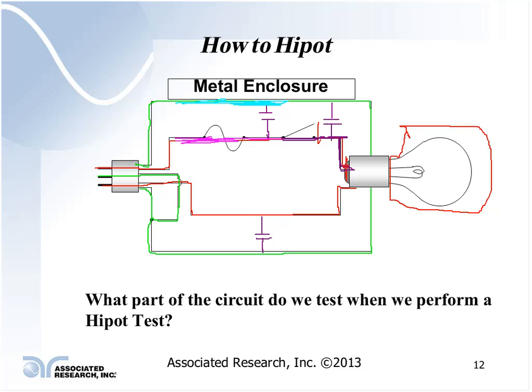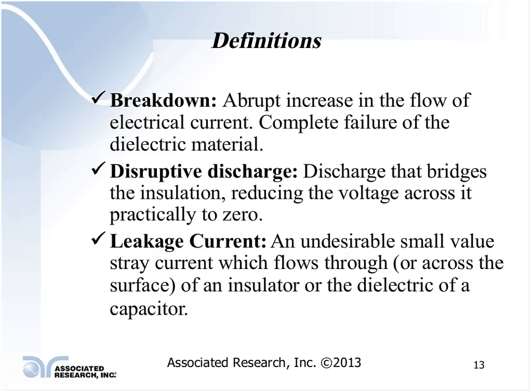Now, if I'm doing a DC test, we have what we call a charge low feature that also can measure the charging current that occurs whenever I initially start my test. And in many cases, I can tell whether the device is connected or not during the test. Okay. So it's important to go through and, again, set your limits properly.